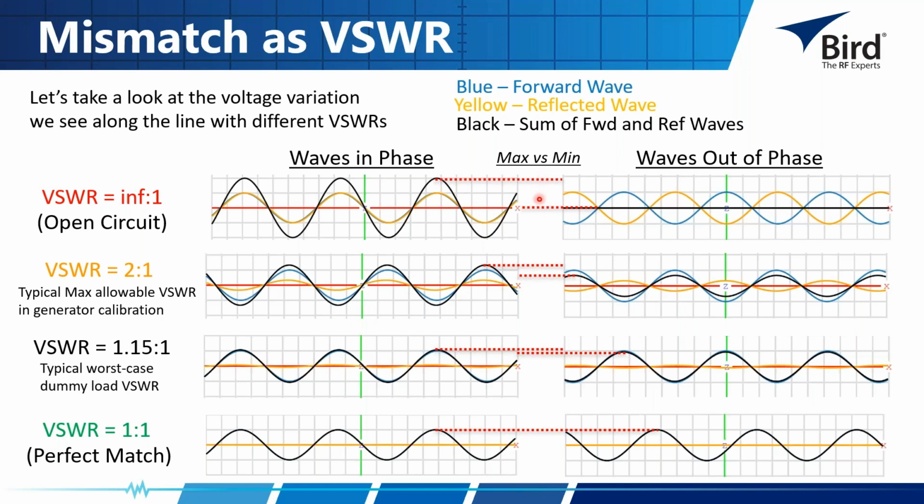Now, when we're thinking of a VSWR of 2 to 1, I bring this one up typically because, especially when I'm working with the guys on the semiconductor side of things, this is really where we do the cutoff on what our sensor can do, where we can have the assurance that it's going to maintain accuracy. We're going to talk about directivity here in a minute, but a VSWR of 2 to 1 means you're going to get about 11.1% reflected power back just due to impedance mismatch. You can see we're starting to get a little less variation here.